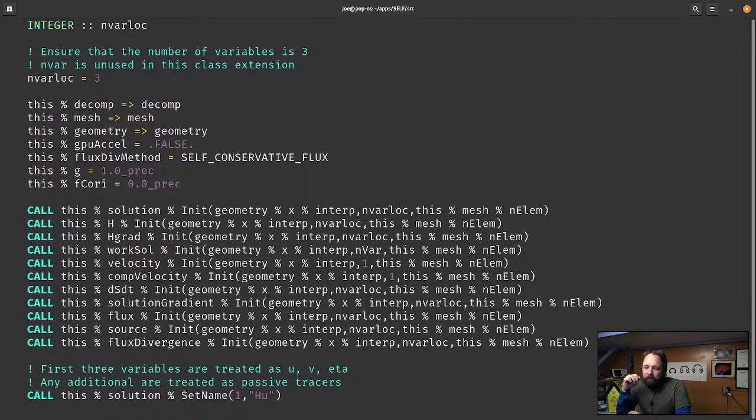So yeah, volume flux, you're absolutely right. It should be meters cubed per second, but we're looking at volume flux. I need to think about this one while I'm coding here to figure out how to phrase this appropriately. But essentially, you're looking at an infinitely thin fluid column where we're tracking h times u, which if you were to integrate that quantity over a line, you would get meters cubed per second. So you're right, I guess it's more like a volume flux per unit length. Thanks for pointing that out.